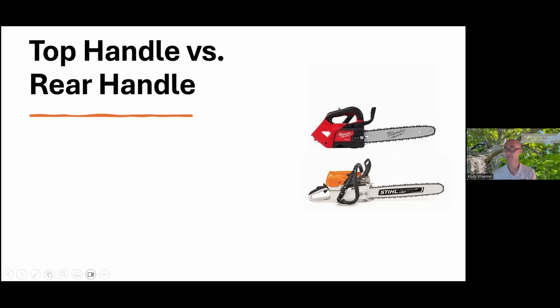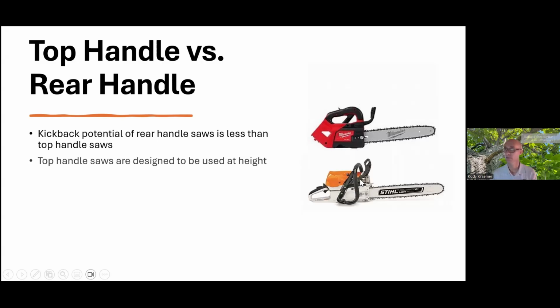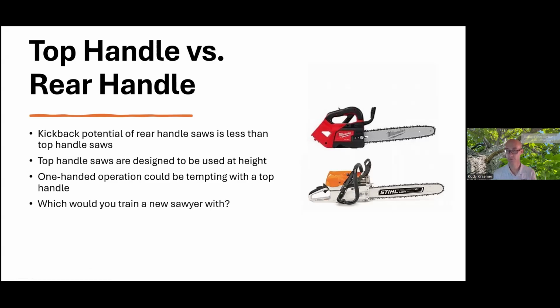So for me, it's important to explain the kickback potential of rear handled saws is less than top handled saws. And it's tempting to want to use a top handled saw one handed. It just is. For me, I would want to train a new sawyer with a rear handled saw. The kickback potential is less.